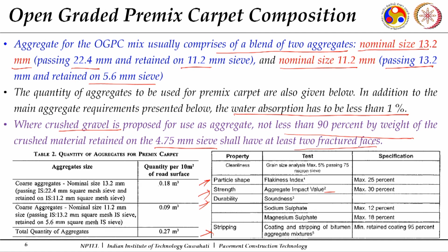So, this is why I call them a recipe mix, because the quantity of aggregate and the quantity of binder, which have been arrived at from a lot of experience with these mixes, are directly given. You do not have to work out any design and combination here. The recommended values are already provided based on the experience with different kinds of aggregates, which has been gained throughout the country at laboratory and field scale.